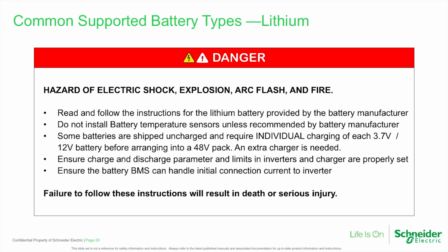Again, you have to make sure to follow the instructions from the lithium battery manufacturer on all things. We use battery temperature sensors. We give you one with every thing that we have that charges batteries, but don't use these things on lithium batteries unless the battery manufacturer tells you to.